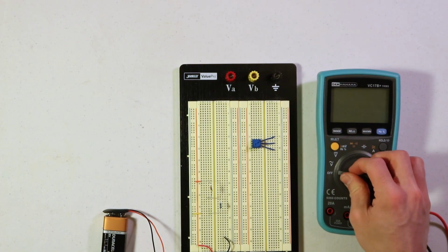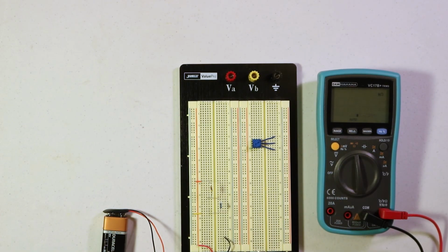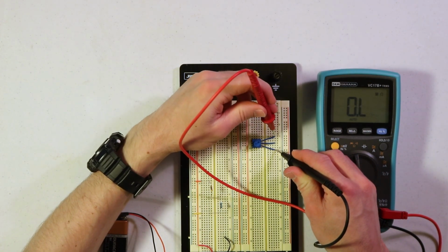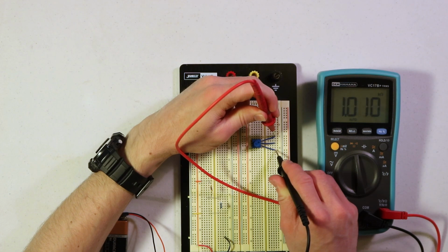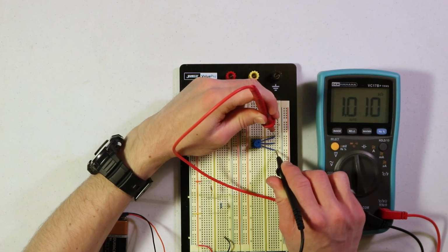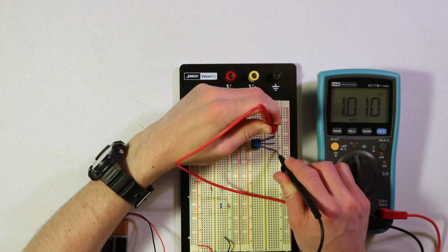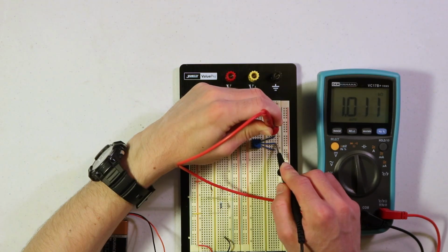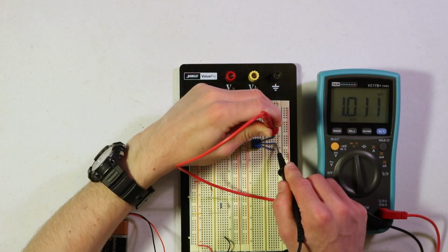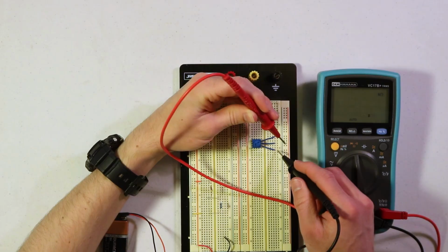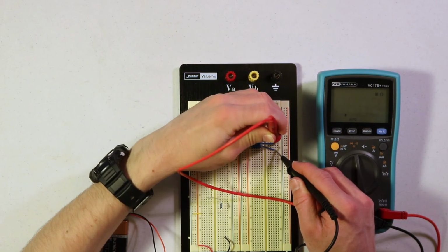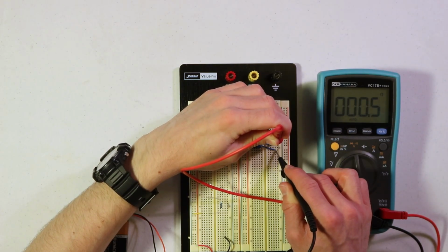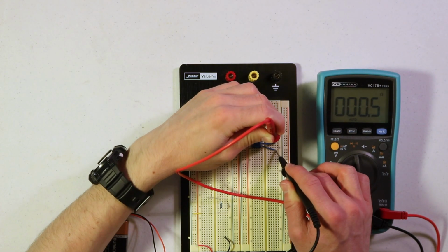So now if we check the resistance, we can set our multimeter to measuring resistance. And let's just check the resistance across pins 1 and 3. So if we look at that right now, we're seeing the entire resistance, about 1 kilo ohm. And then we can check to see what the resistance is between, say, pins 1 and 2. So right now we're seeing the full resistance across pins 1 and 2, which would mean we should see about 0 resistance across pins 2 and 3. And like we would expect, we've got very low resistance, or almost 0, for pins 2 and 3.